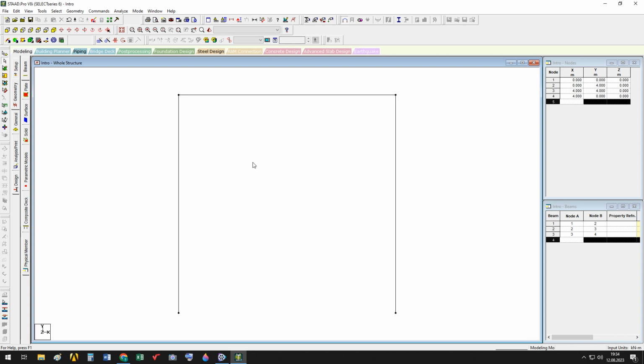In general, in the literature, we structural engineers know that beam is one element, column is another element, and some elements are beam column elements. But in the Staad Pro program, beam is a jargon term, and beam is given to all frame elements,